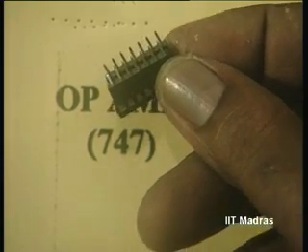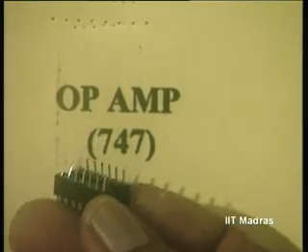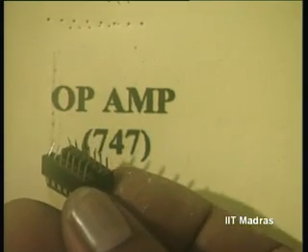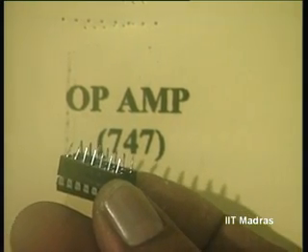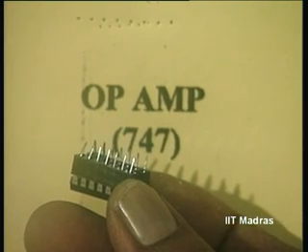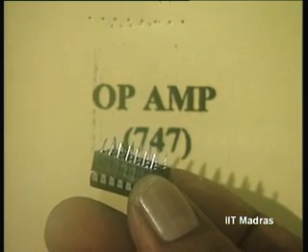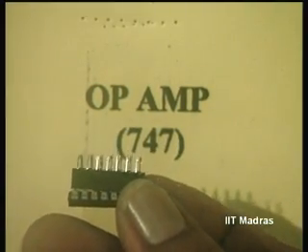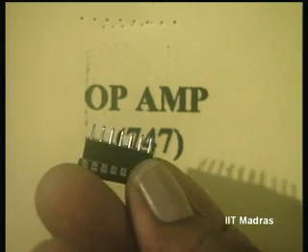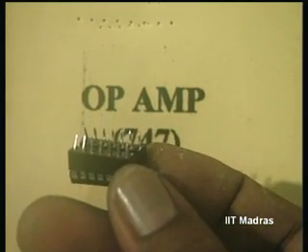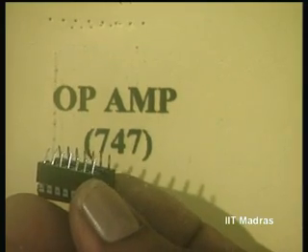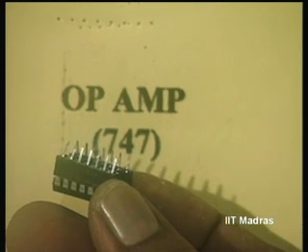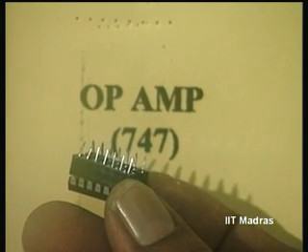Now, each operational amplifier will have 2 input terminals, differential input, 1 output terminal, so 3 terminals, and 2 power supply terminals for the dual supply to be applied. So, 2 plus 1 is 3, plus 2 is 5 terminals essentially, and if there are 2 such op amps, we will have 10 terminals taken care of. In this 14-pin package we have the possibility of what is called offset compensation, about which we have also discussed. So, 2 terminals for one op amp and 2 terminals for the other op amp for offset compensation.